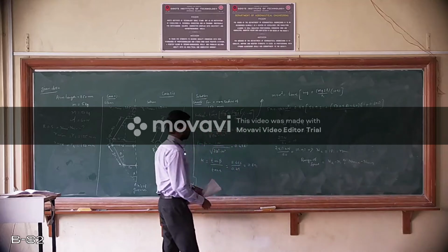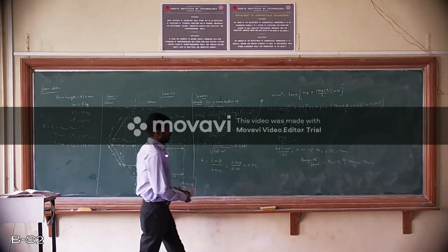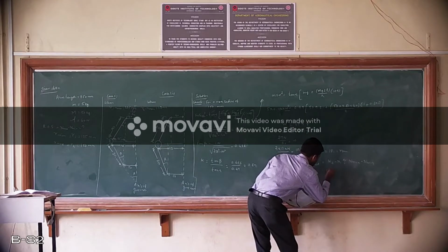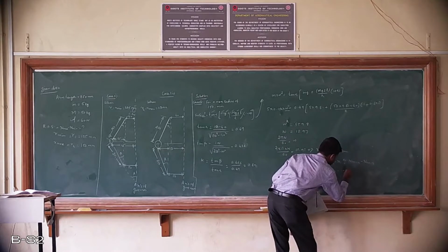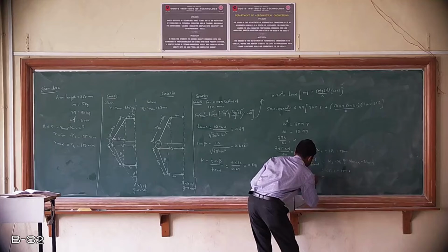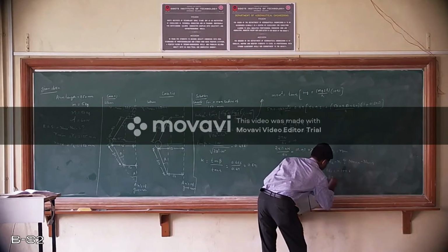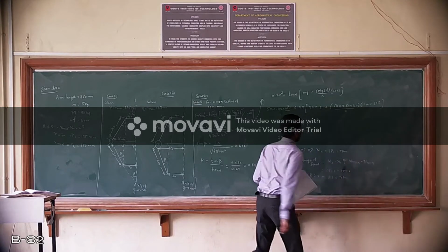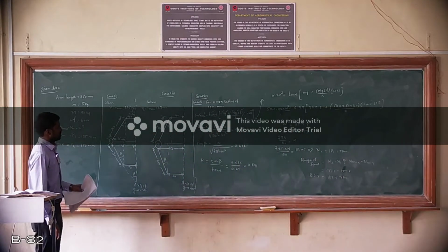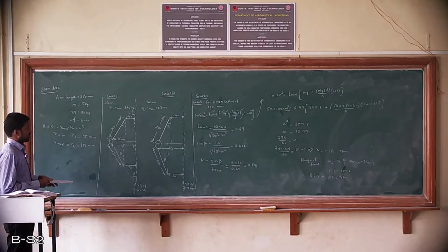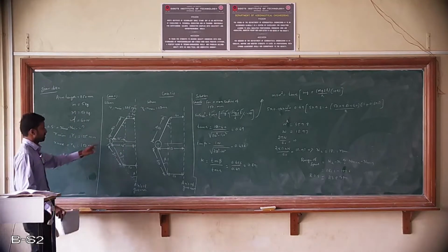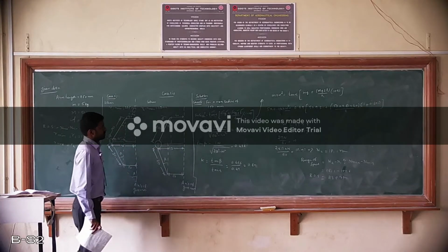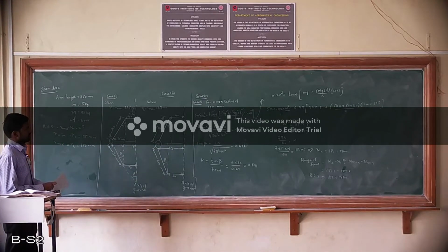So what is the value for n2? The value for n2 is 181. Already we have calculated, minus the value for n1 is 157.6. So the value for range of speed is 23.5 rpm. So this completes the problem on Porter governor, where both the arms are not pivoted on the axis of the spindle. So this completes all the problems, all the varieties on Porter governor.